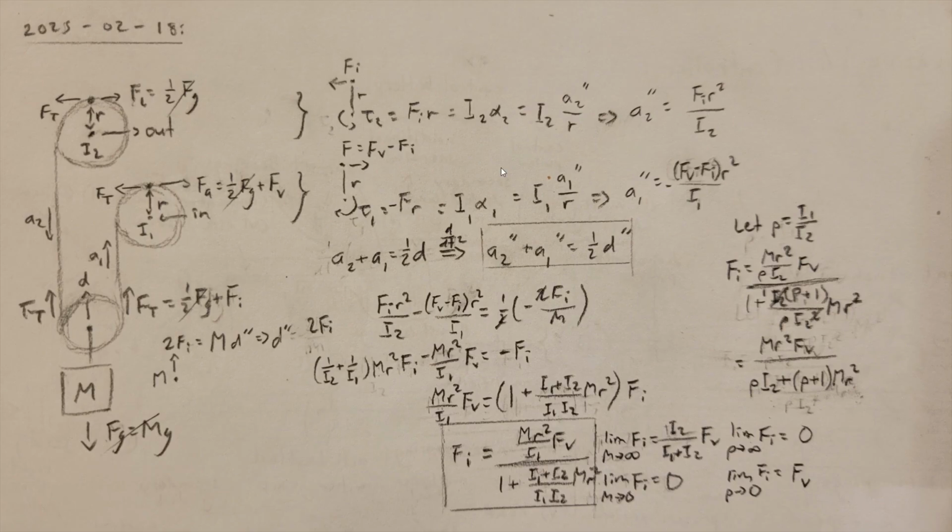Here we have an analysis of the Huygens Drive's performance. The details are shown for reference, but what is important is the outcome. This analysis assumes the input and output sprockets have the same radius r, that the input and output sprockets are coupled to moments of inertia I1 and I2, that the tension contributed by the Huygens weight's mass is completely cancelled out by the input and load at all times, and that the auxiliary tensioning weight is negligible.